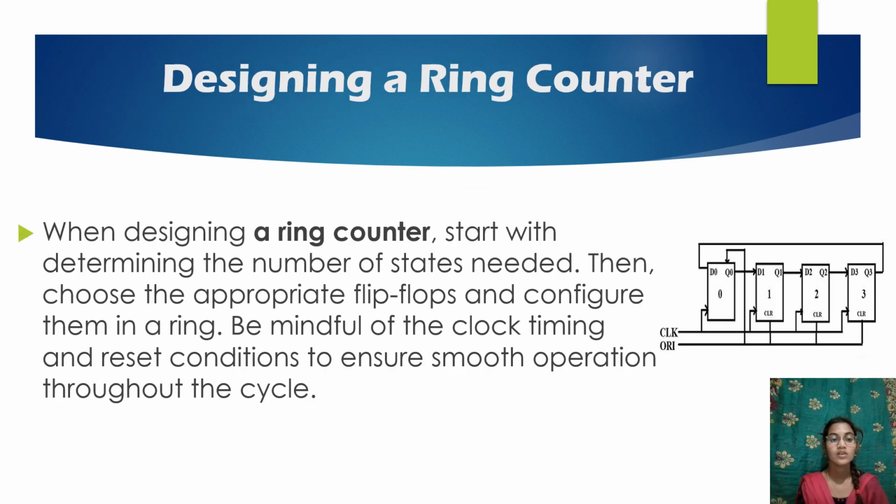Designing a ring counter. When designing a ring counter, start with determining the number of states needed, then choose the appropriate flip-flops and configure them in a ring. Be mindful of the clock timings and reset conditions to ensure smooth operation throughout the cycle.